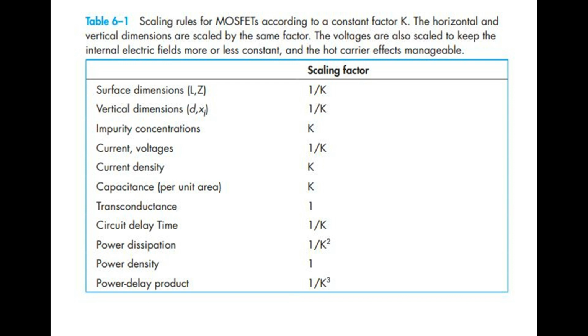Scaling factor of transconductance 1. Scaling factor of circuit delay time 1/K. Scaling factor of power dissipation 1/K squared. Scaling factor of power density 1. Scaling factor of power delay product 1/K cubed.